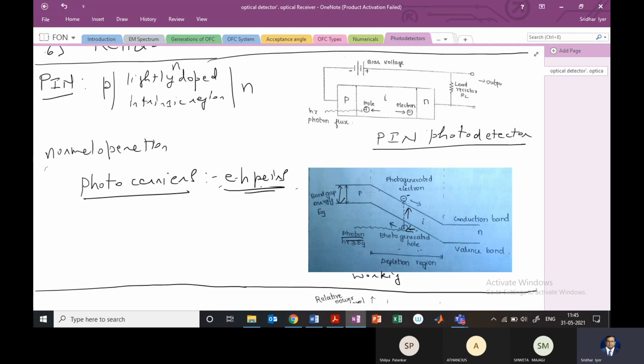So now this photodetector is designed such that carriers are generated in the depletion region, and most of the incident light will be absorbed. So all of this is going to happen in that I region there. So this I region is going to be very important. How have you doped it, how much light is going to be absorbed in there, all that needs to be known there.